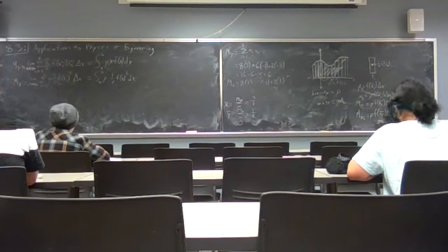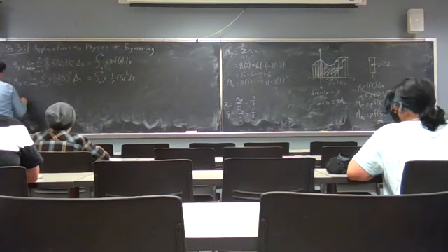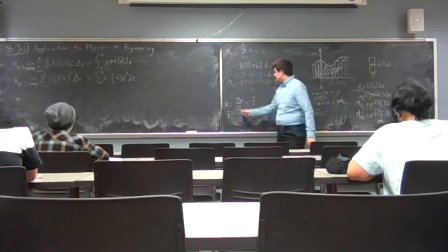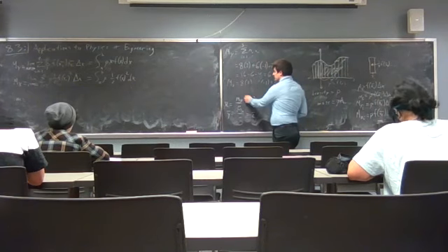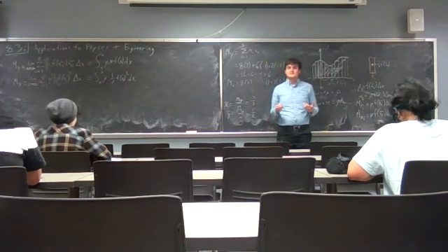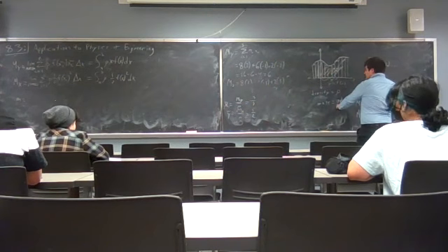Good. So we get that. Now, let's think about the mass of our object, right? Because we said to get the centroid in the 3-point case, we took the moments and divided by the mass. Well, the mass of the object is just the density times the area.